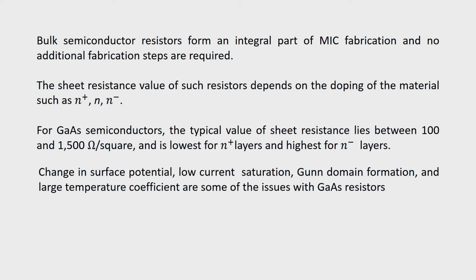Now, gallium arsenide resistors have some issues, and these are change of surface potential, low current saturation, Gunn domain formation, and large temperature coefficient.